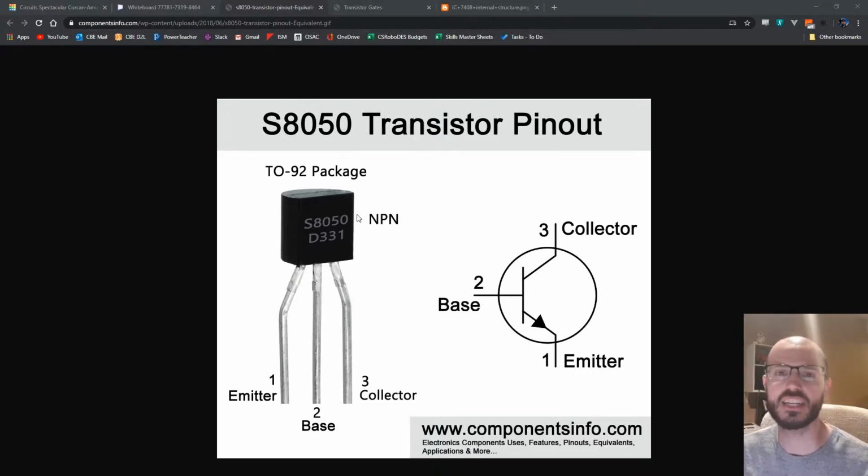A transistor is essentially just a switch. It's something that allows current through or not, depending on some state. So just like the light switch in your room, it allows current through to the light bulb if you've flicked the lever up, and if you flick the lever down, it doesn't let any current through. Transistors work in the exact same way. They let current through if some condition is met, and they don't let current through in any other case. With transistors, what needs to happen for it to let current through is for another pin on the transistor to be experiencing a voltage. So it's an electronic switch that is triggered by more electronics.